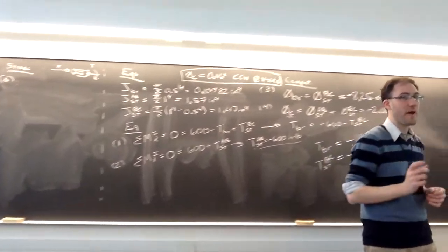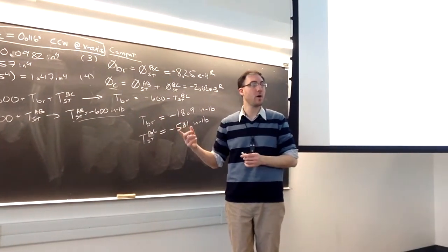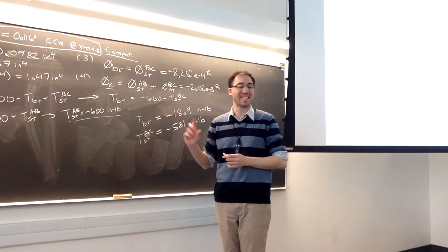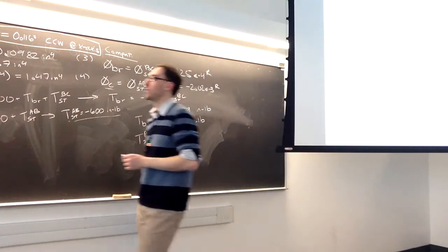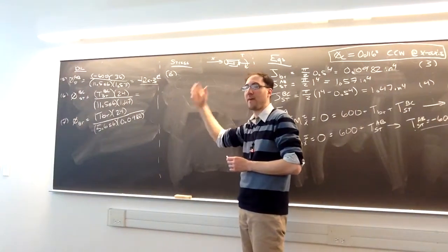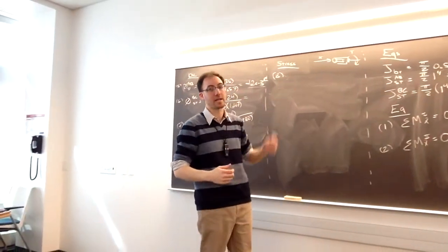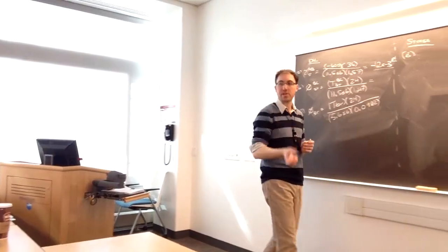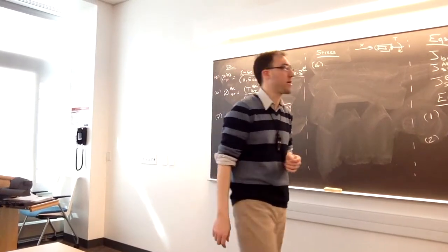Our interpretation of our angle of twist is that the angle will be in the opposite direction of T when the angle is positive. It'll be in the same direction as the torque when it's negative. So it's negative, our T is going counterclockwise around x. That means because we have a negative value, the angle of twist is also counterclockwise with respect to the x-axis here. Right? We also want to know in each material, what's the maximum shear stress that it's going to experience.